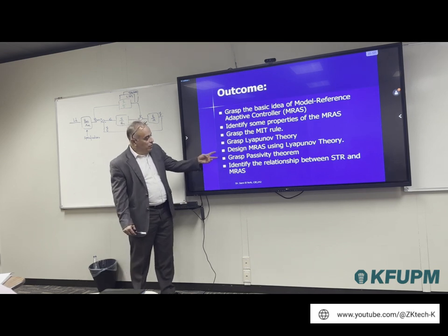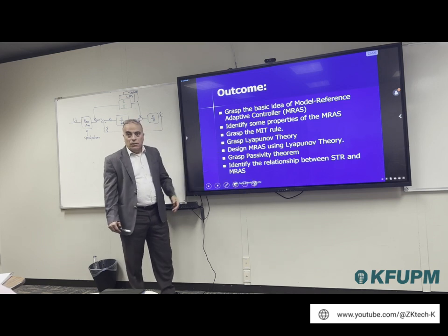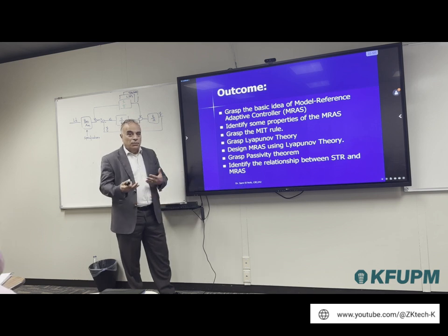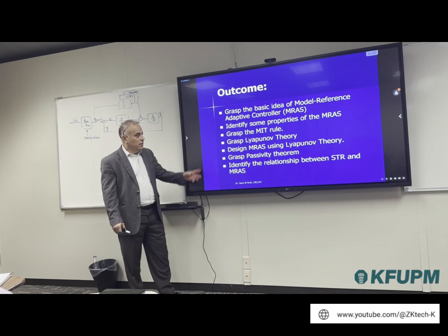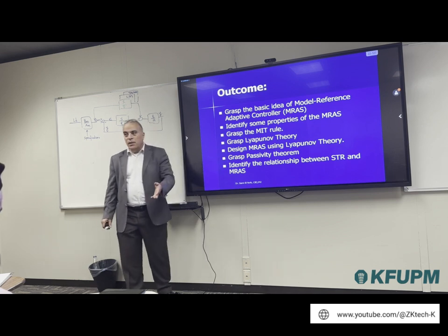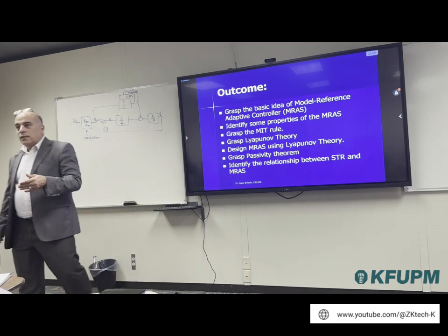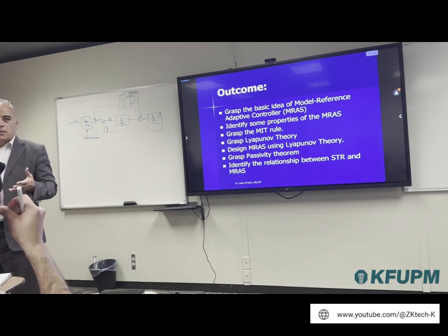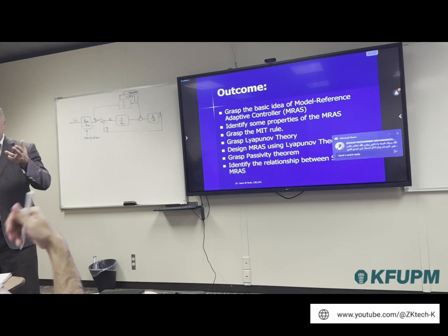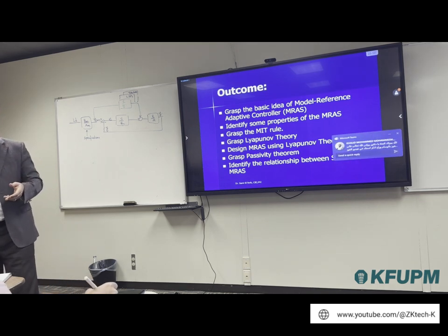So if you would like to go to multivariable, this would be one of the cases that we are going to use. If you don't have decouplers or anything that separates your system into single input output, then you need to go to it, otherwise it will be complicated. Now, the problem with this approach is that it's basically a state feedback. It's no longer an output feedback. We are no longer looking at the output of the system and trying to do the control based on that.